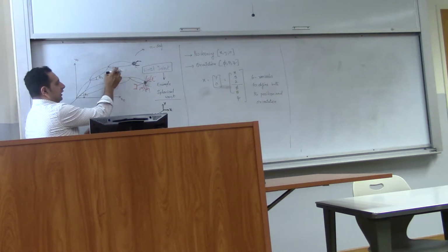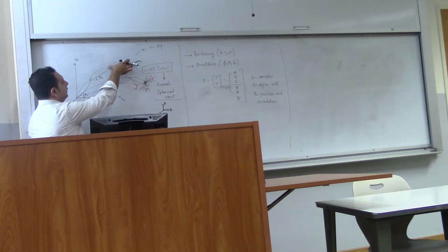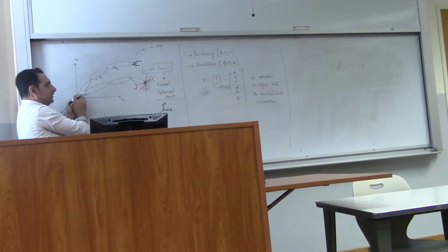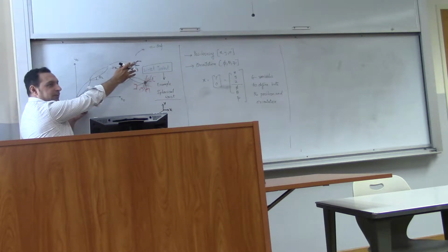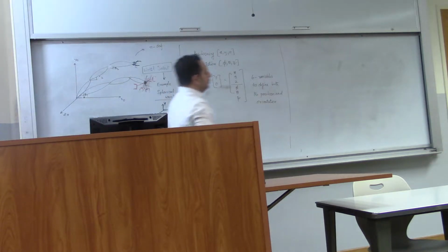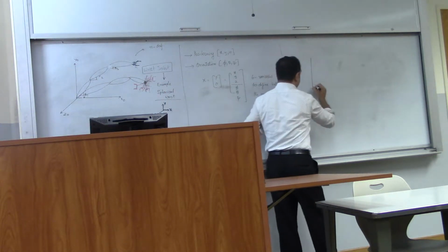Okay. If I move theta 3, let's say I change theta 3, the end effector will move, right? So if I change this, it can go up or down. Does it affect the previous links? No. But if I do change this, all the consecutive links are going to be displaced, right? Because if I move this, the whole chain is going to move. So we need to associate a frame for every joint.